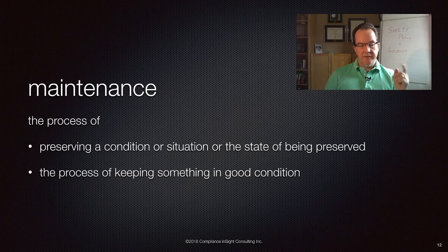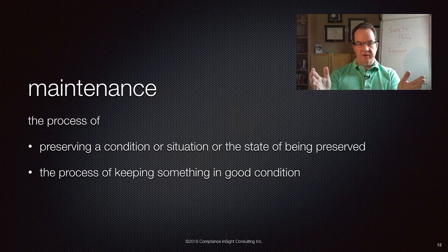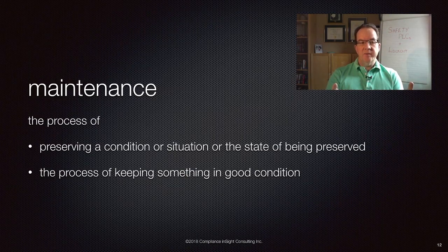Now, interestingly, Z460 does include the word blocking as part of a lockout procedure. So it's one element that can be used as part of preventing unexpected startup. So if you're going to follow the regulations, anytime a worker's safety might be endangered by the starting of a machine or by hazardous movements, then the movements need to be blocked and the energy sources must be locked out.